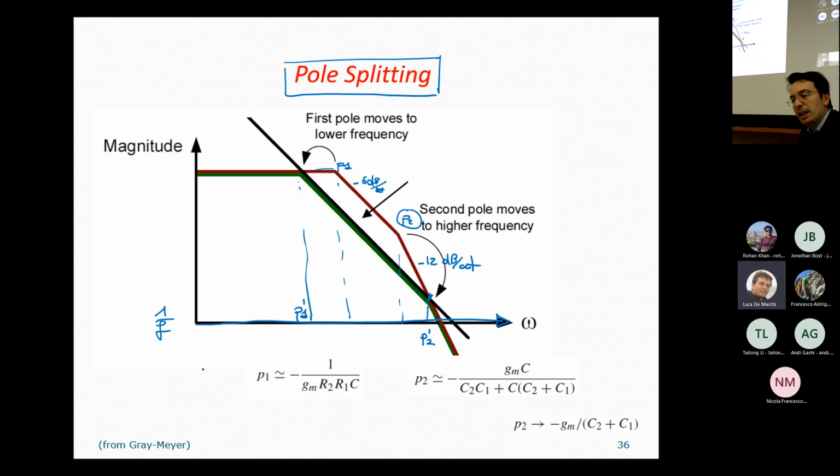Now let's see what happens when we apply a negative step function, or if you want, when we apply a positive step function to this terminal here. So basically, in this case, all the current generated by transistor number 5 flows through this branch. No current flows in the other branch because of the unbalancing. And the current mirror indeed mirrors the input current at the output.